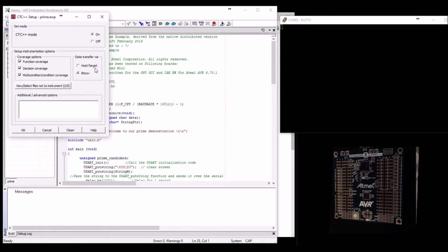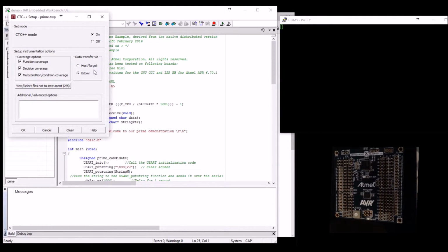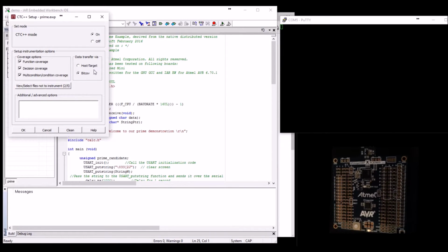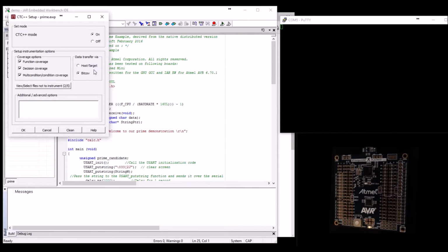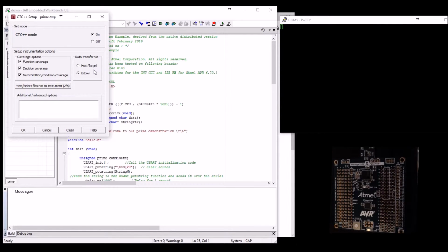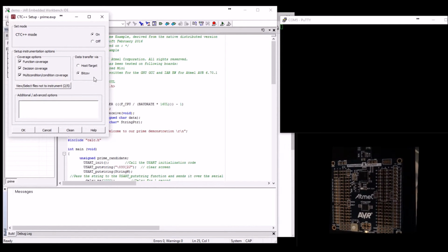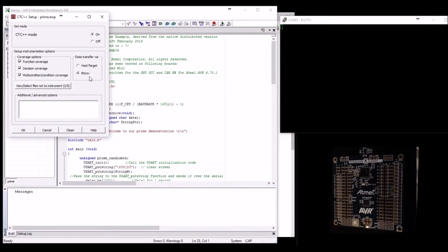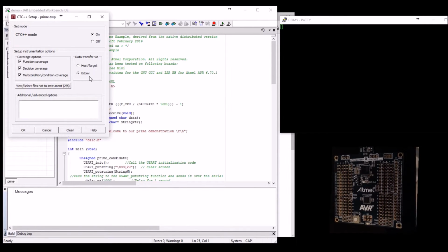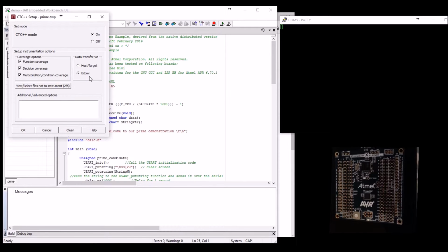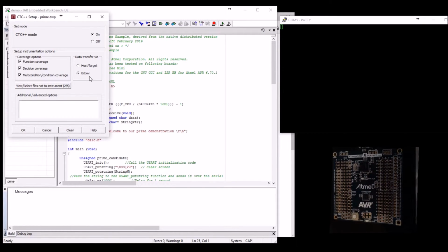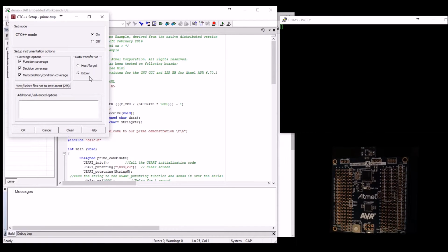So it could be host target, which means that you will have your own functions to save the data on the target using the hardware you want. Or the most efficient way, if you have an access through JTAG like today to the target directly, is to use bitcov. Bitcov is simply storing all counters values to this global variable.